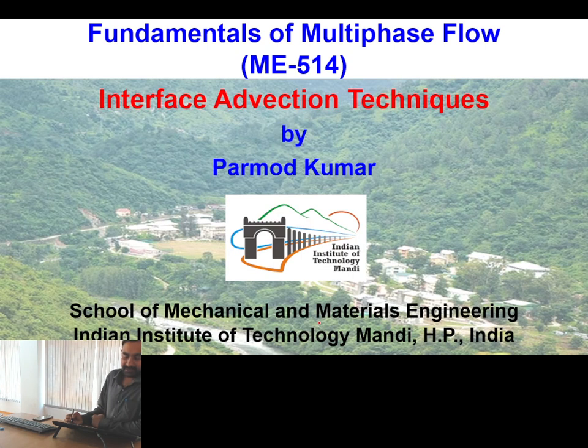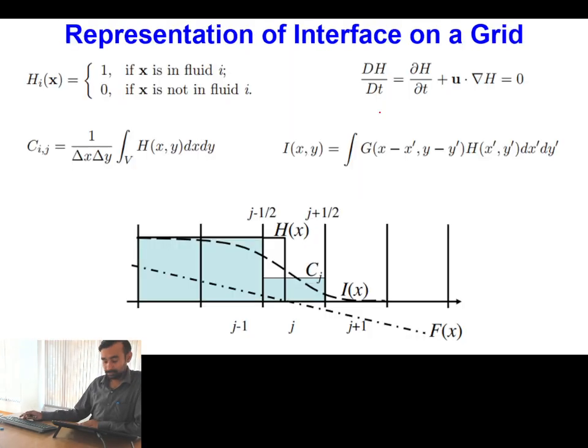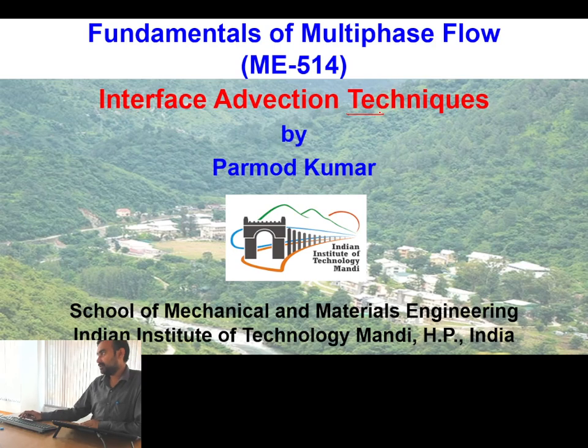Okay, so good morning. We will today discuss the interface advection technique. If you recall, in the previous lectures, we discussed how to mathematically define the interface. Once we mathematically define the interface, as I told you earlier as well, that particular interface will be evolving with space and time. So once the interface is evolving with space and time, depending upon the normal interfacial velocity, we have to devise certain numerical schemes which can help us in advection of the interface.